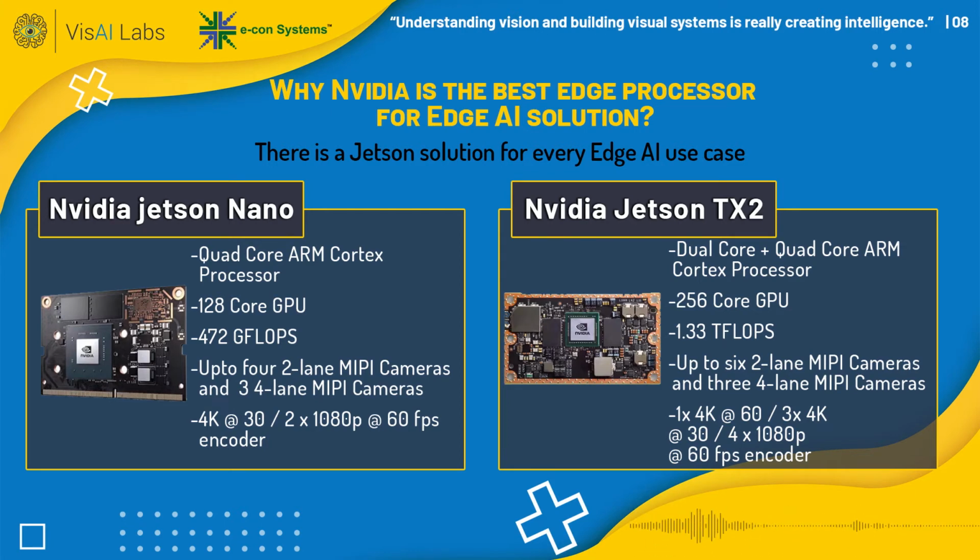The next, better-performing processor is the Nvidia Jetson TX2. It has multiple cores, one quad core and one dual core, and it is twice as good in terms of GPU cores and more than twice as good in terms of the inference engine, the FLOPS. And it can have up to 6 cameras. Some of our customers are already in the field with 6 cameras, and all the 6 cameras can stream full HD at 30 frames per second.